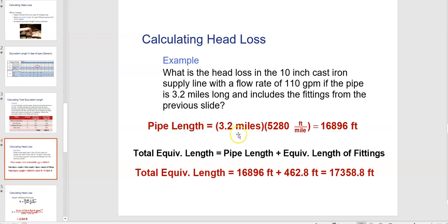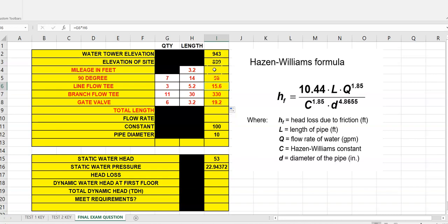So you'll see we have 3.2 miles. There's 5,280 feet in a mile. We're going to do a unit conversion real quick. So when we're here in Excel, I'm going to hit equals, and I'm going to type in convert. And I'm going to double click on convert. You're going to notice it kind of bleeds over into this. Now I'm going to have to type in H4. I'm in cell H4.